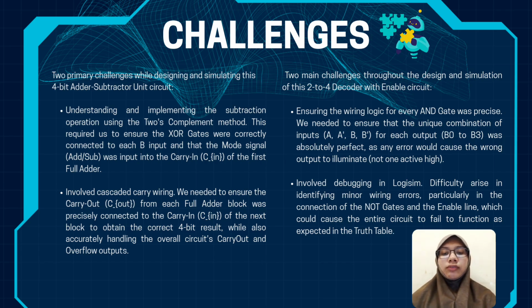This circuit involved cascade carry wiring. We needed to ensure the carry out from each full adder block was precisely connected to the carry in of the next block to obtain the correct 4-bit result, while also accurately handling the overall circuit's carry out and overflow output. Next is the 2 to 4 decoder with enable circuit.